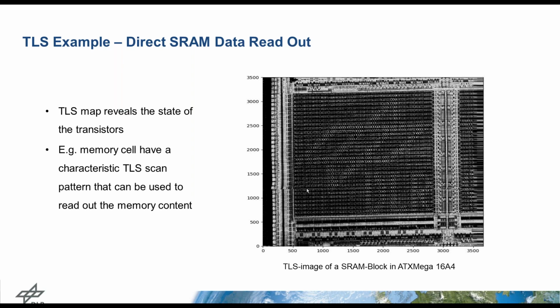And we can here also not only scan memory cells, we see the state of a transistor. This tool can be used for failure analysis too, because here we use a wavelength that is not absorbed by the substrate. So that means you do not have to thin the substrate for this kind of measurement or analysis. So this is a great tool. So this was the last of the laser techniques.